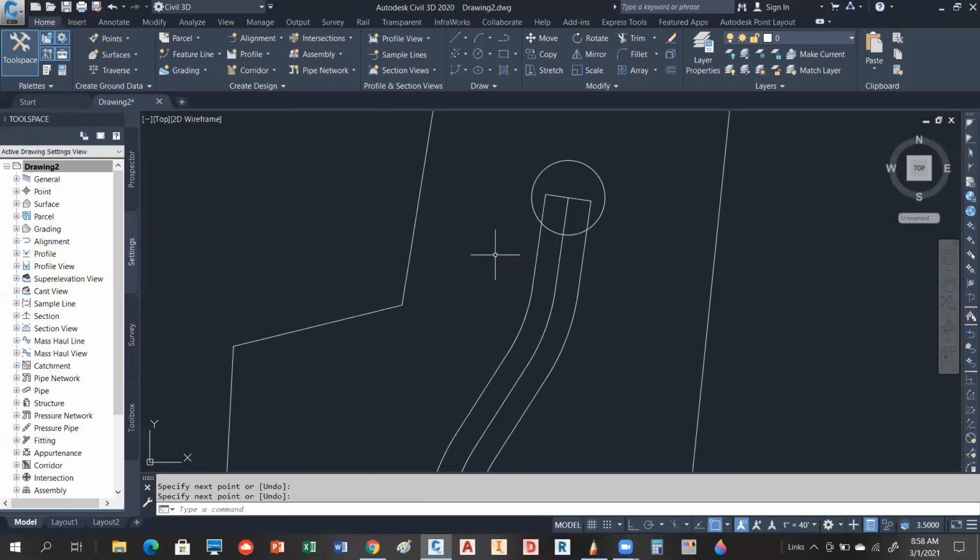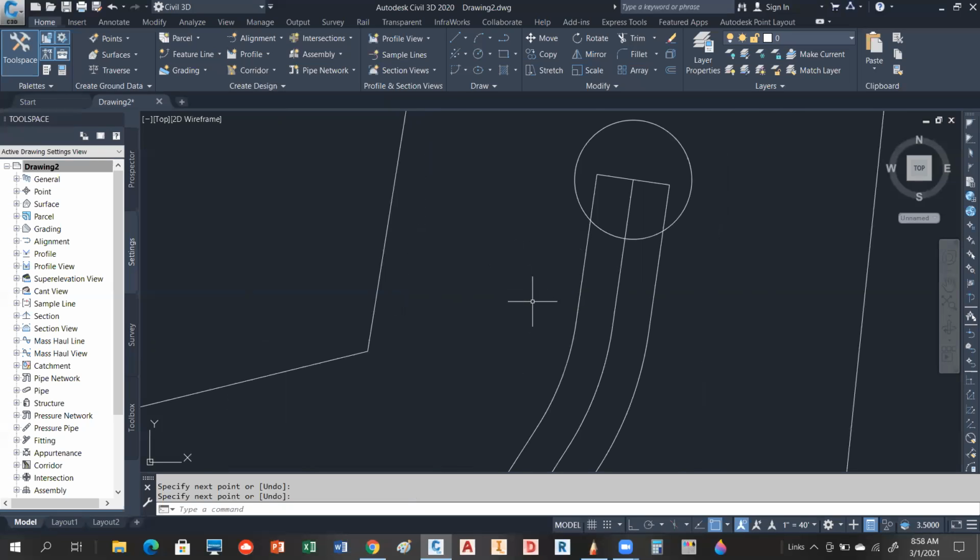If you have a cul-de-sac detail, the detail is that the throat starts 75 feet back this way. So I'm just going to do another offset, and my offset distance is going to be 75 feet. I'm going to select this line and then come back 75 feet. In any municipality, every cul-de-sac is different. This was the standard cul-de-sac they used to use in Hamilton County. I'm not even sure they still do, but it probably is done correctly that way.